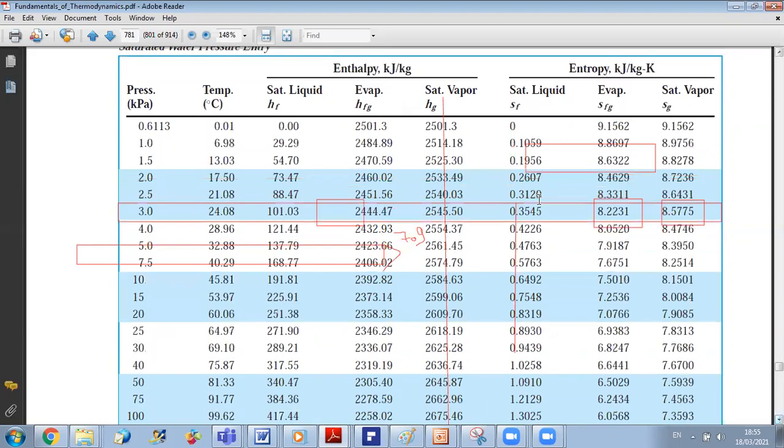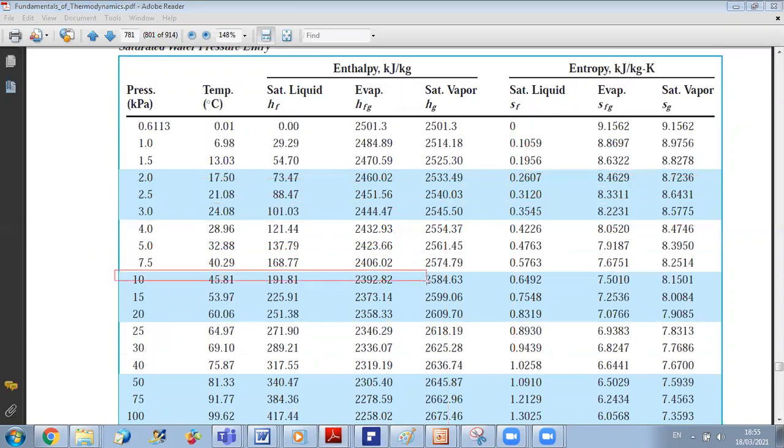This is the line of interest. Now, from this line, I will read the corresponding values. I can find the quality from this line because I know that S is nearly 7.89. Since 7.89 is relatively close to 8.15, I expect to have a quality larger than 90%.